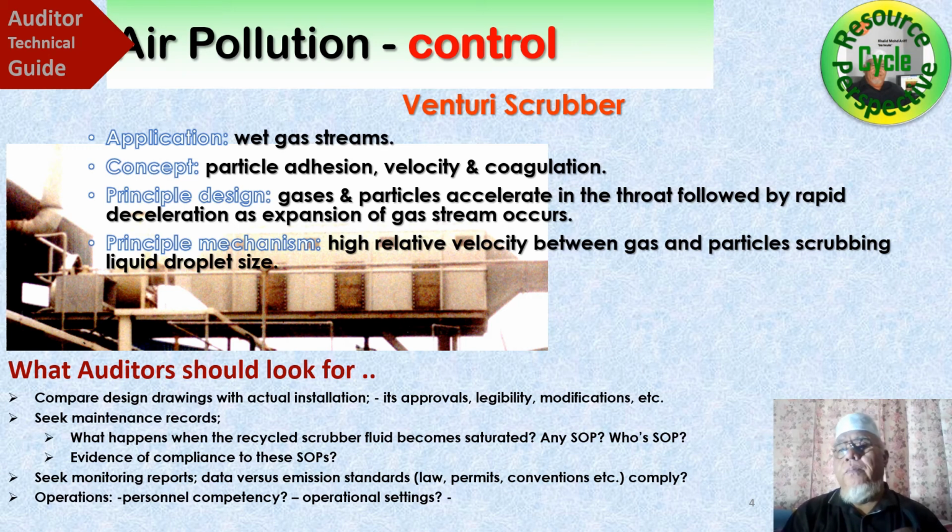I was told by the operations personnel that this layout or configuration was due to the presence of microscopic metal dust in the acid fumes extracted from its process origin. In reality, scrubbers are usually customized to the types, nature, and characteristics of air pollutants that constitute the incoming wet or gas streams.